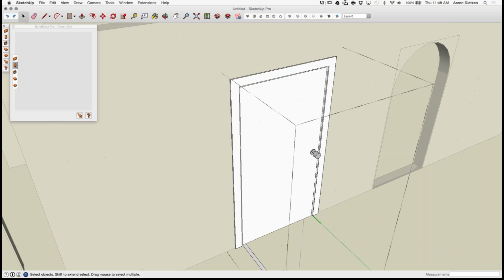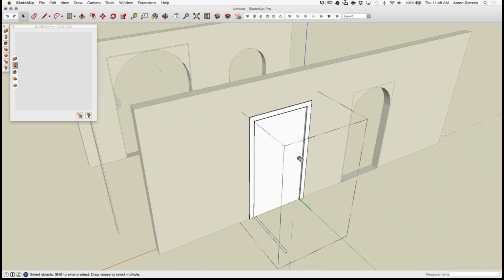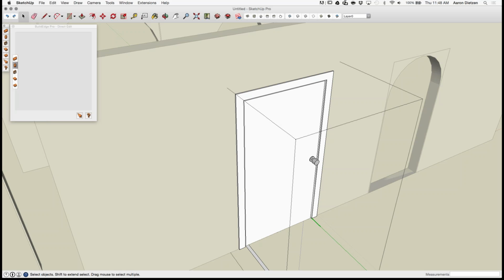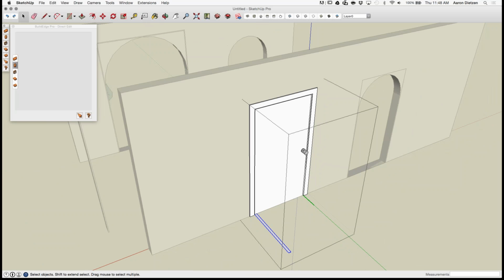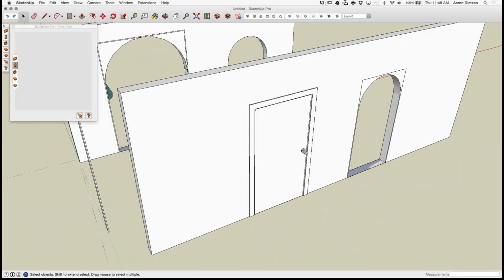It's your SketchUp model. You can do whatever you want. The downside to that is it's one-off. I can make those changes one time, and it's not going to save. I can't put them in the next model. I can't put it into the next wall. But this could be edited on an individual basis. So if I didn't want the 2D swing, for example, I can select it, delete it, and it's gone out of this instance of this door this one time.